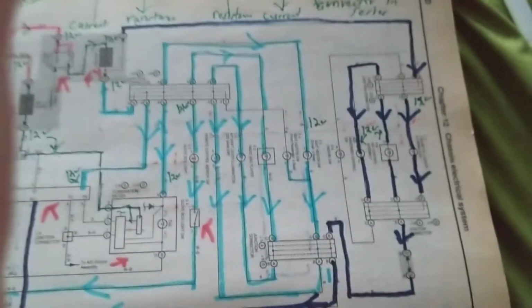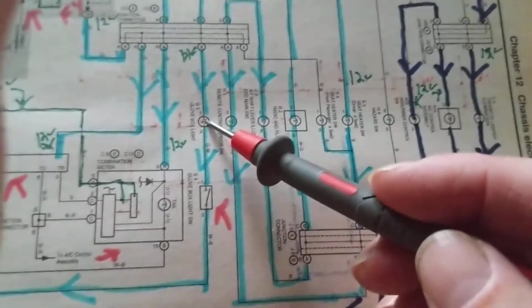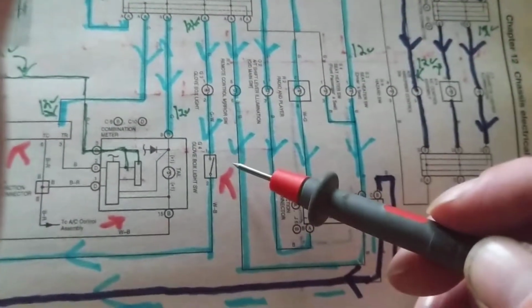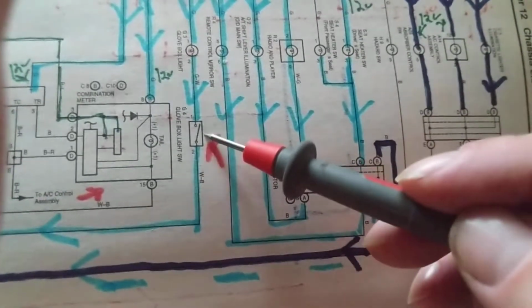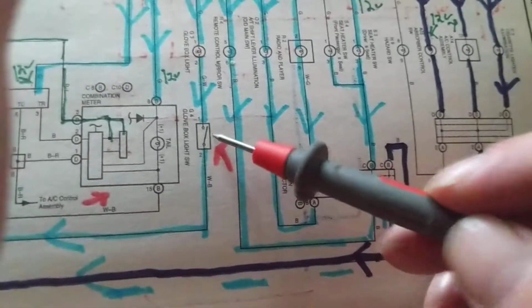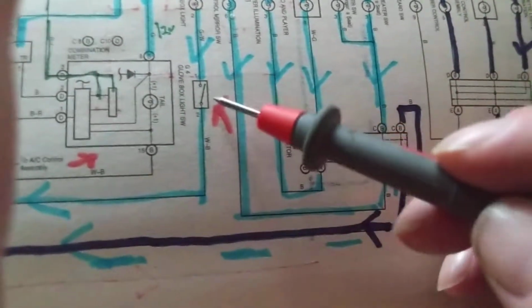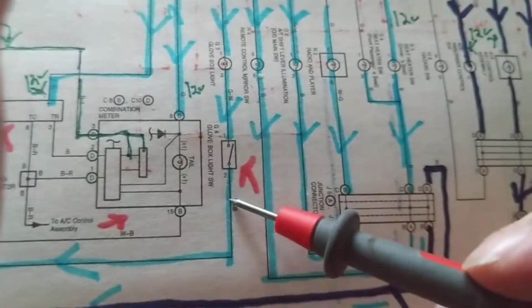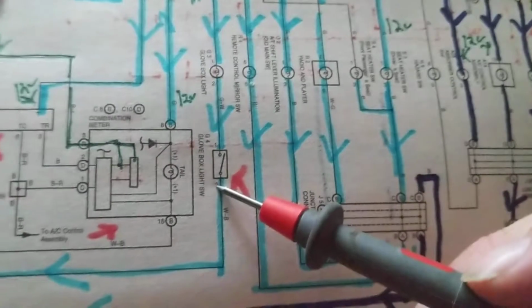Question, where else do you find a switch? A normally open switch in the schematic. Technician A says, this is a switch. Technician B says, this is a switch. Who's right? Technician B is right. This is a switch. Is this normally open or normally closed? This is normally open. In the rest position, the default, I call it the default, it is open. If it's open, current cannot flow. If it's closed, right here, from here to here, current can flow.